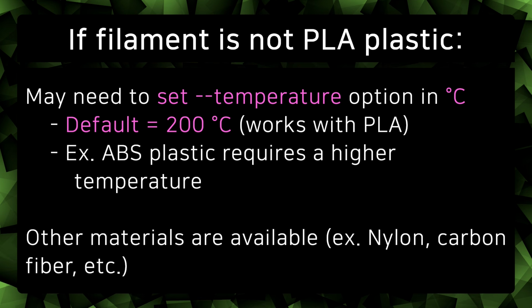The default temperature is set to 200 degrees Celsius, which works for PLA plastic, which is a common filament. Another common filament is ABS plastic, which requires a higher temperature to be used. Note that there are other kinds of filament, such as nylon and carbon fiber.